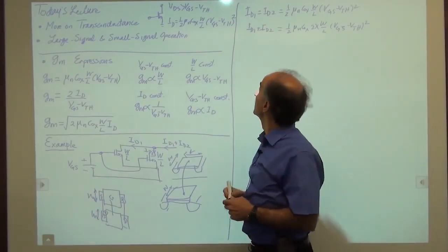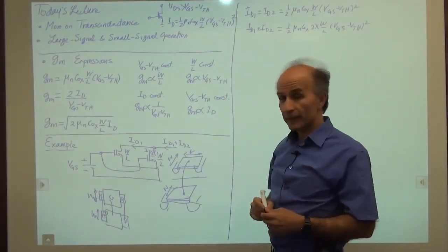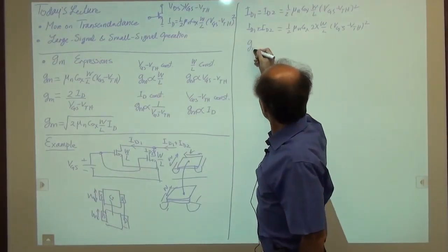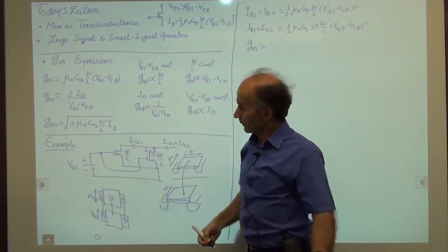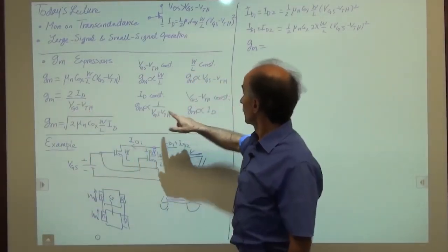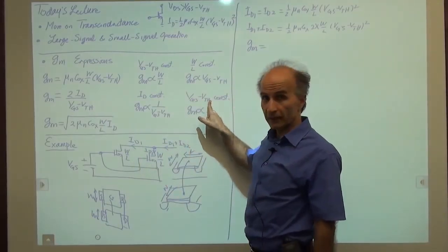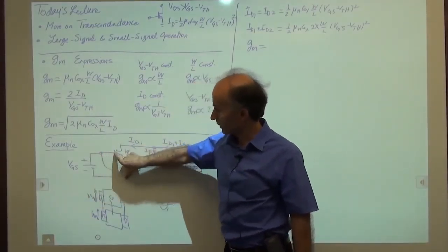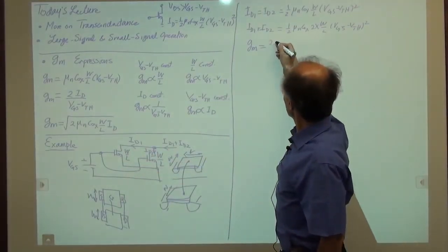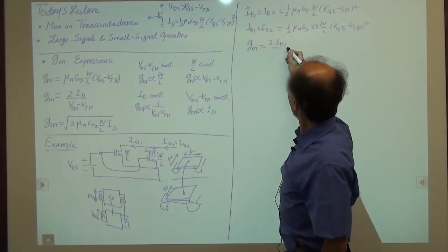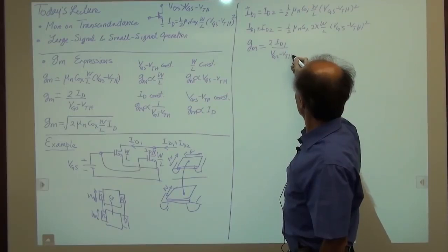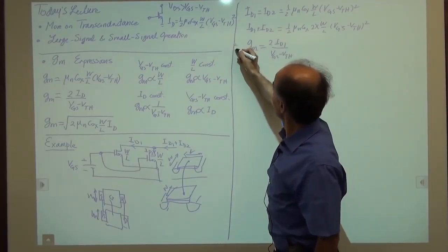All right? Okay. So now what happens to the transconductance of the device? Well, we write GM. We can try to use any of these. Perhaps the simplest one is this one, because we kept VGS minus VTH constant, right? They have the same voltage. We just added one more device. So GM, which was 2ID1 over VGS minus VTH, this is the old GM.